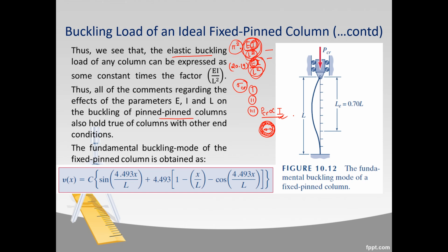And as a fourth comment, we talked about this in our previous lecture also, our Euler's formula is valid only for long columns, that is columns whose slenderness ratio, that means L by r ratio, leads to a critical stress below the compressive proportional limit, or for our case compressive yield stress, as we saw in our previous lecture diagram at last when we discussed a diagram regarding L by r and sigma CR for two materials.